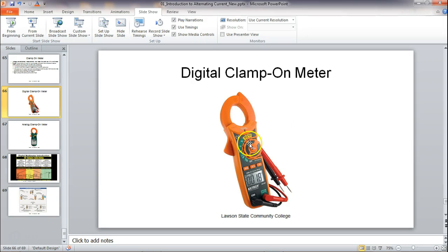Now what you'll find usually on these clamp-on meters is that the minimum clamp current is around 40 amps. So these are sure enough high current devices. What you need one of these for, if you're in the electrical trade, not the electronic trade, this is the meter you need to get. So you need to buy a nice clamp-on ammeter, not necessarily true RMS.